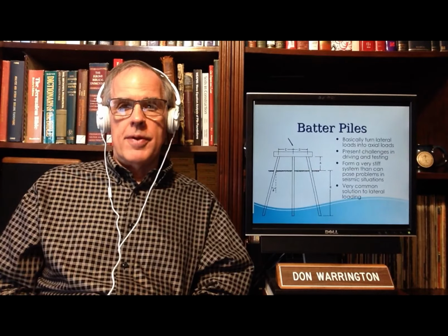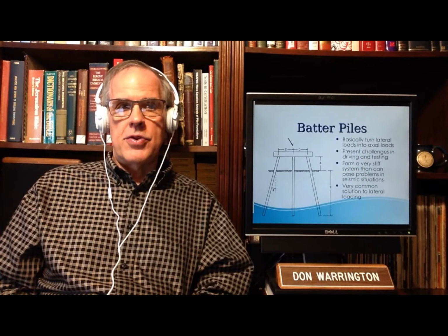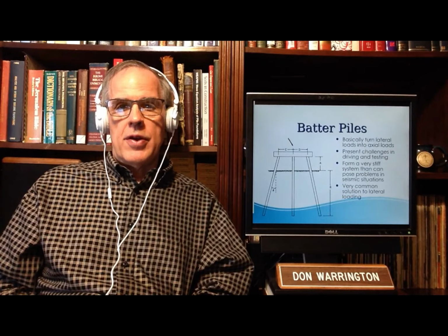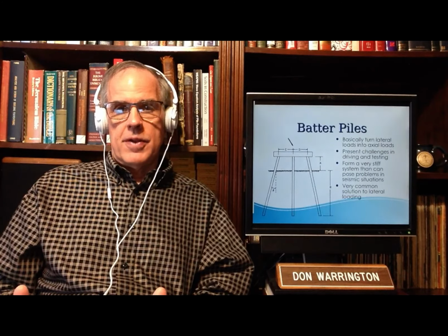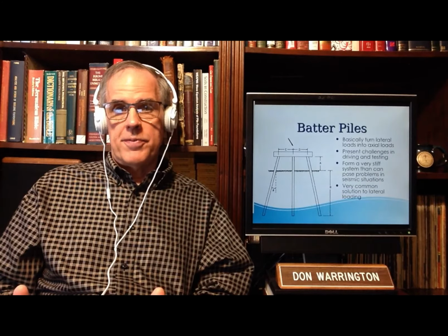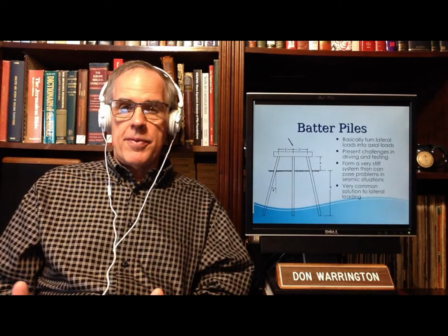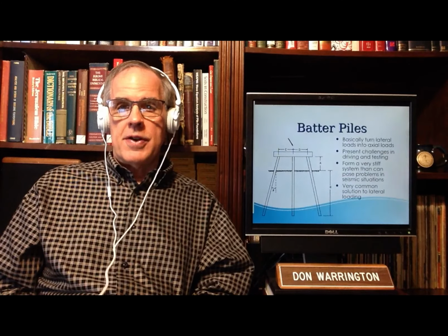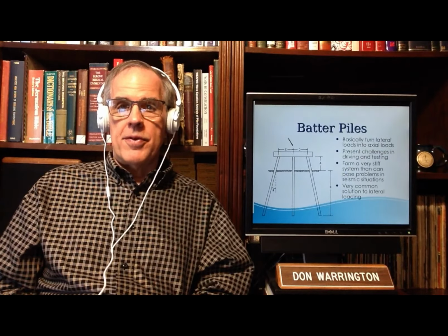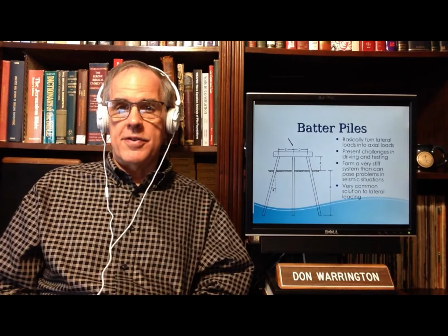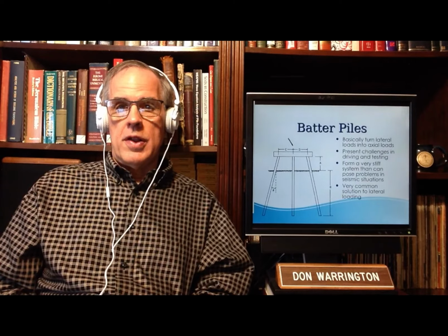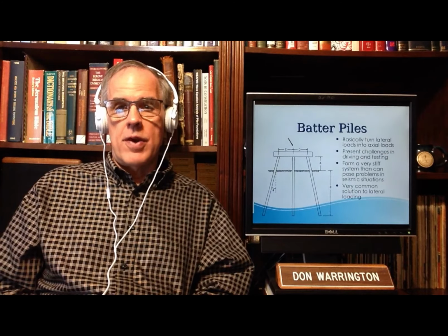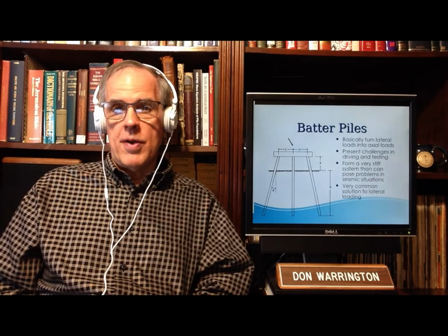The other problem is that batter piles tend to withstand lateral loads in a very stiff fashion, in other words, without a lot of deflection. In some cases, that's fine. In some situations, particularly in seismic, that can be a real first-class disaster, because the stiffness of the system will lead to catastrophic failure if whatever lateral loading happens overwhelms the system.